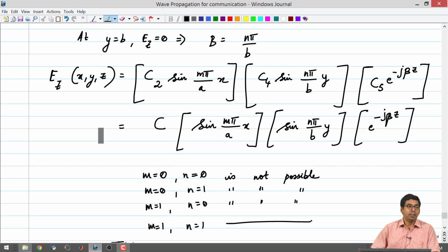And so, the fundamental mode, or the least value of m or n that is possible for you to give a non-zero value of Ez, the way that you had started, Ez not equal to 0, was the way you had started. You cannot end with Ez equal to 0 because that is in contradiction of the assumption you made in order to get to this point. So, the solution which corresponds to Ez not equal to 0 requires you to place some minimum criterion on m and n. So, m and n are 1 and 1, and the corresponding case will have some spots in your waveguide.